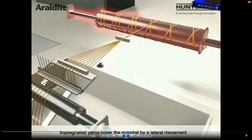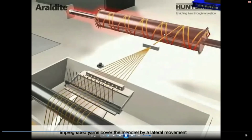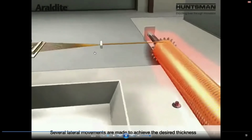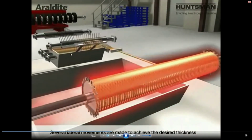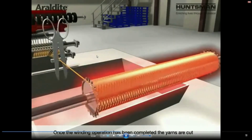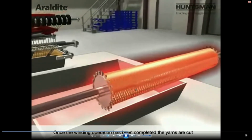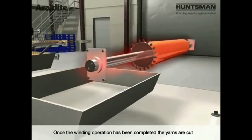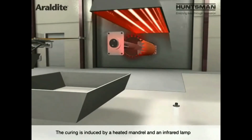The red color signifies that it may be under the hot condition or the heated condition. The impregnated yarns cover the mandrel by the lateral movement. This is a lateral movement. You can see this is a lateral movement of the resin bath or the carriage. Once the winding operation has been completed, the yarn is cut, it keeps on rotating, and finally we will take this mandrel, hot mandrel, for curing process.